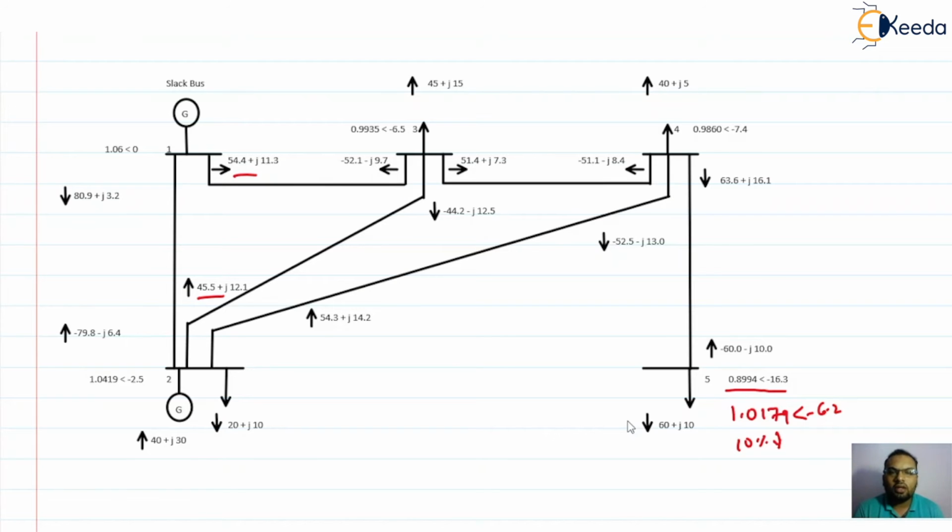So this way we can get to know the variation in the voltages on the buses and the variation in the line flow. We will get to know from this whether there are any violations. Violations in the sense that the voltage should not get more than the prescribed value, or less than the prescribed value; it should be within that prescribed range. Again, the loading on the line should not exceed its thermal and static stability limit. If it exceeds, then there is a possibility of line failure, so that we have to analyze.